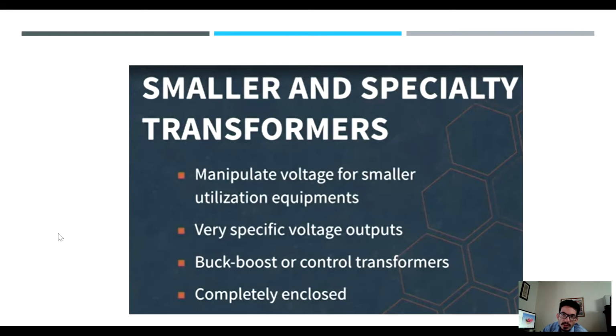So the transformer uses 120 volts AC, and the building supplies 108 or 110 volts to that particular side of the building because of losses, inefficiencies, size of wires, etc.